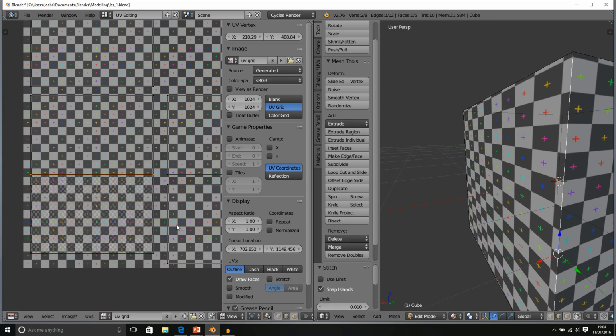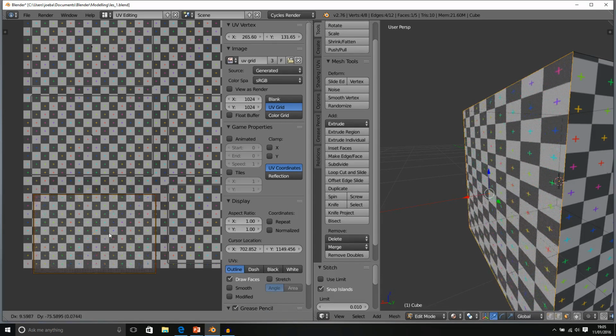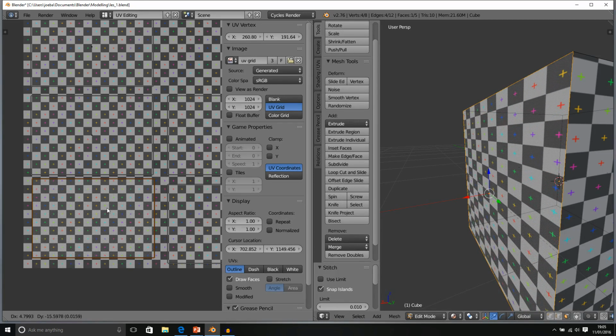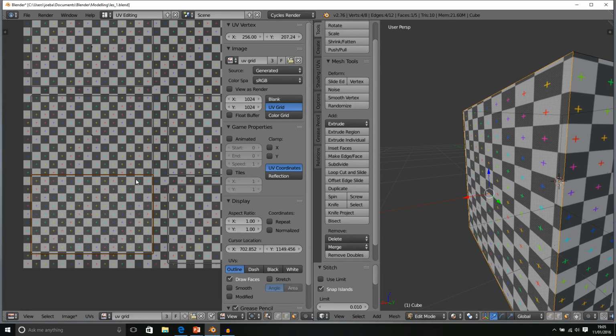So two things have happened, one on each panel. The first thing that happens is that the two selected edges on here have joined up to become one. Now we can still select these faces, and we could still actually select and move these faces. So they haven't merged together, they've just stitched together. So I'm going to press escape to cancel.